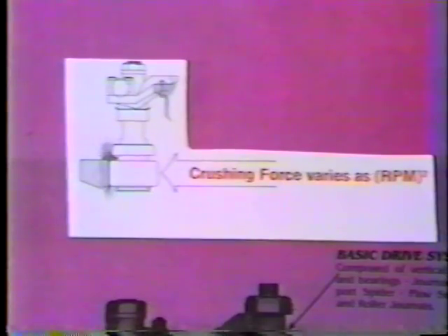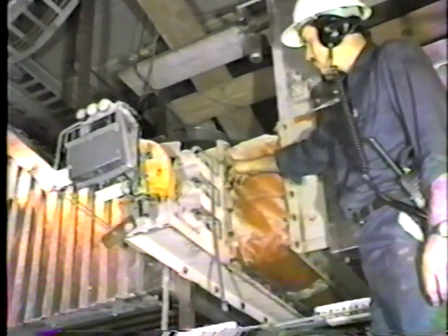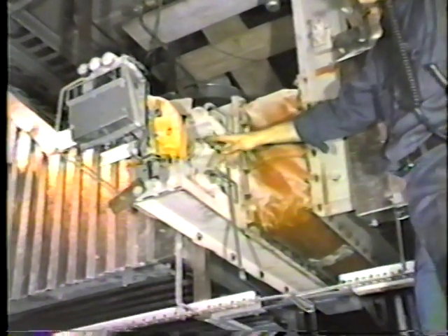Capacity adjustment is achieved from 100% to 0% output by varying the central rotational speed. Since centrifugal force varies as the square of the rotational speed, production will increase or decrease accordingly. Air is used to dry and convey the pulverized coal.